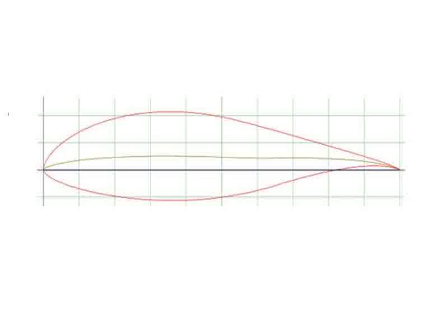For the assignment, it was stated that the chord length for the wing should remain constant throughout, so we don't have to worry about any tapering, but for most gliders there would be a taper to get the best efficiency possible and reduce drag.